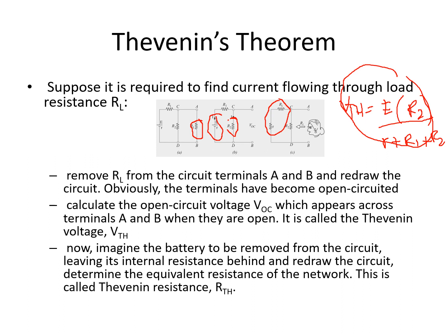Okay, so our RTH now is equivalent to the series combination, that is R plus R1. They are in series, so we simply add them, and they are in parallel with R2. So this is now your RTH.